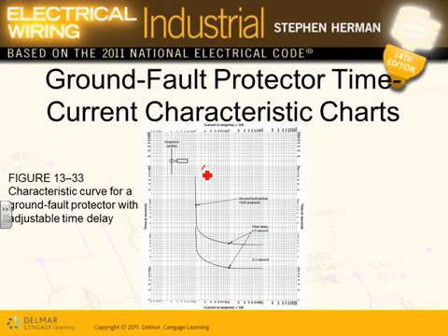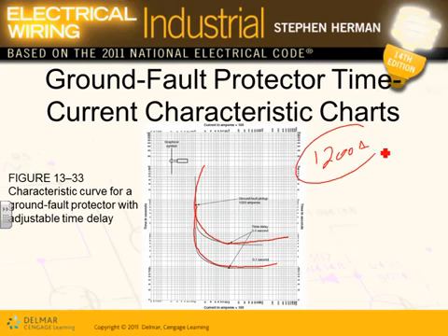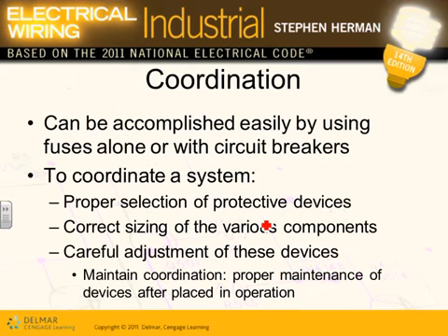Adam, the same thing for ground fault. They also have a curve that you can set. You can set your ground fault if you have 1,000 amp or more. You can't set them at more than 1,200 amp, I believe, but you can adjust and delay that. Look at that. This trips at 0.1. This trips at 0.5 to coordinate between the two.